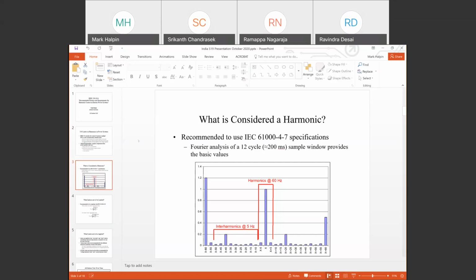So there's a little bit of, you might say, additional content in a harmonic. If you can just watch the mouse pointer a little bit, here's the integer number, and of course here and here are the 5 hertz bins on either side. So what we're going to call in this example harmonic X would be the RMS value of all 3 of these terms, not just the one in the middle.